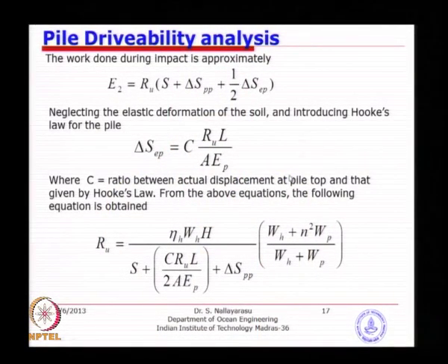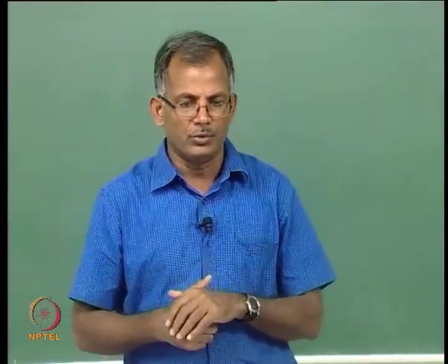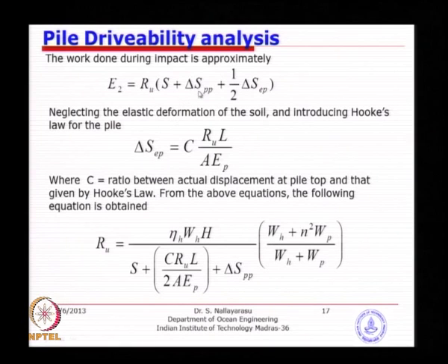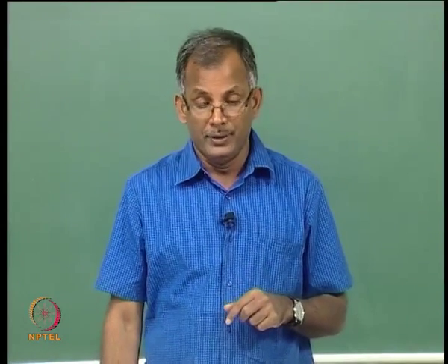and then the work done during the impact, you can take the average value of that elastic compression, because initially it is 0 and at the end of the strike some amount of compression has occurred. Plastic deformation, we definitely do not want to go to that stage. You do not want the pile to be permanently deforming, but in a theoretical case you can have it. Ultimately, when we do the drivability analysis, we will remove this and limit the stresses in such a way that we will not go into plastic and select the hammer accordingly.